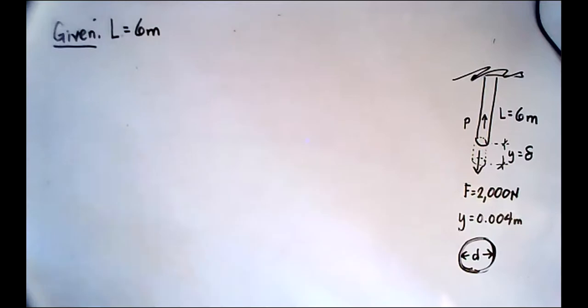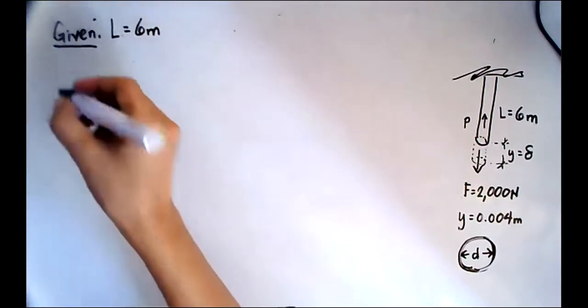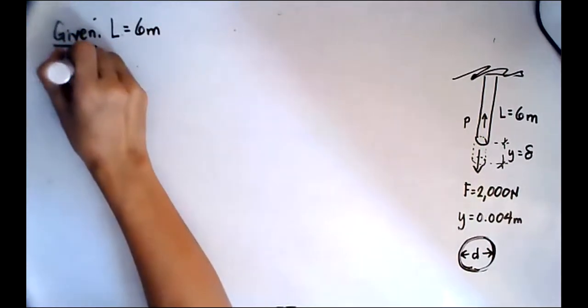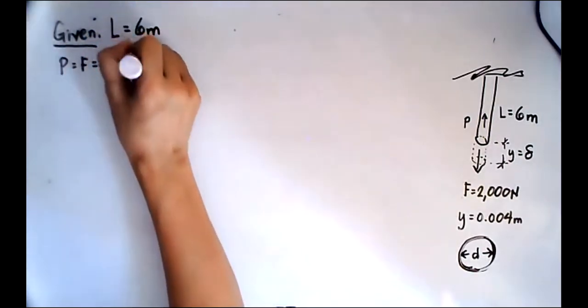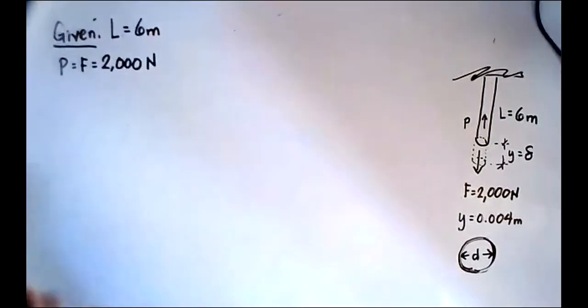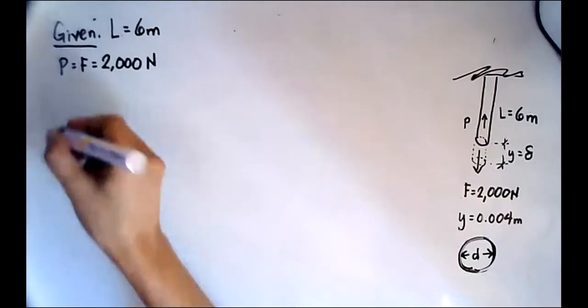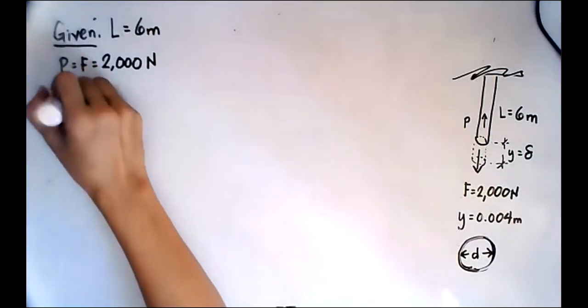We have the load, which is 2,000 Newton, or that's F. And of course, the weight of the wire is to be neglected. We are going to make use of 140 megapascal for allowable stress.